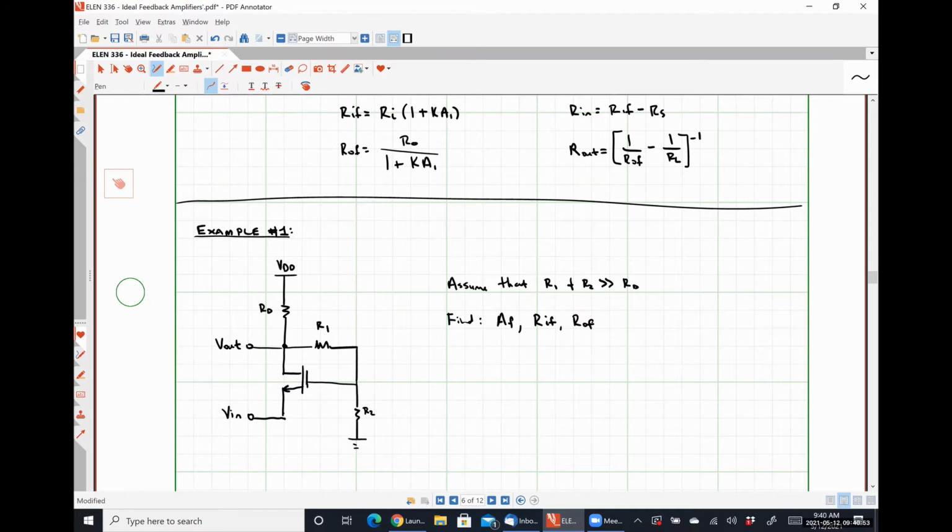We will immediately after this example work the problem and assume that we do have loading effects and see how to treat it in that way. And we'll find out that if we do the math, they are effectively the same thing when the values of R1 and R2 are very large in comparison to RD. I did a MathCAD sheet to literally prove that. So we could actually work all problems under the assumption that our feedback network does load the system and still get the correct answer.